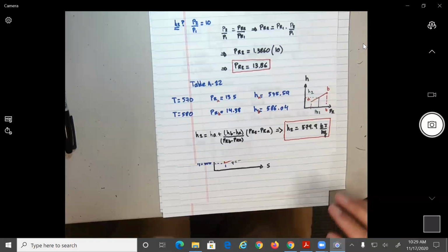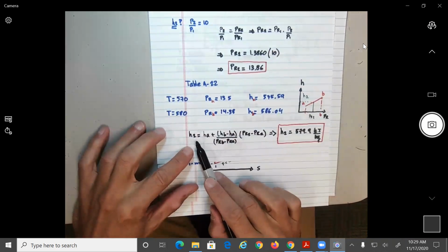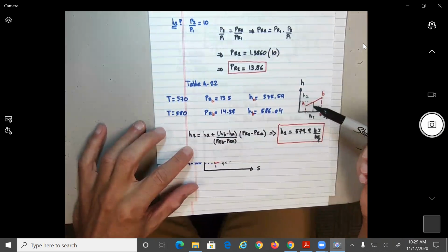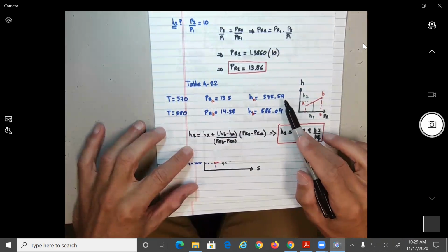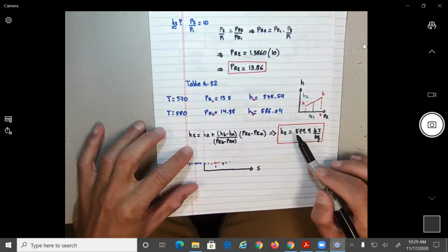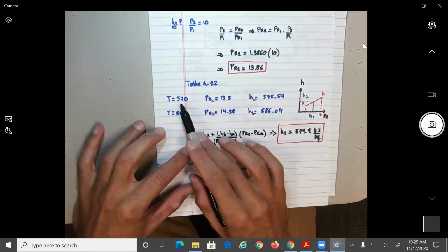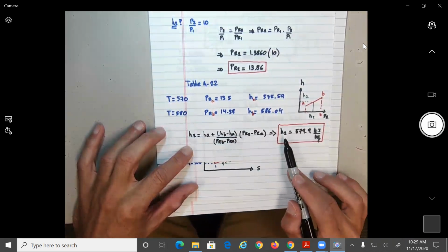All right, so guys, in order to save some time, basically we're going to assume that the variation of the H and the water temperature will be the same, saying that it is the same slope. So I just ask you to divide H2 by H sub A. You tell me it's about 1.07. Is that correct? Okay, so if you do that, now if you multiply that ratio by the T equal 570, you should get T2.